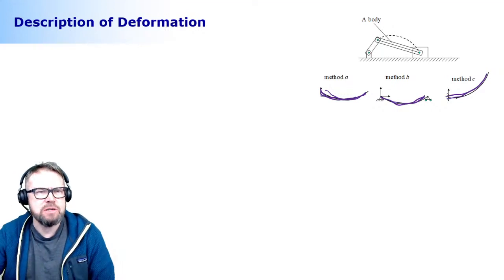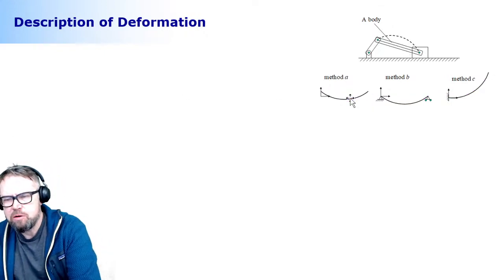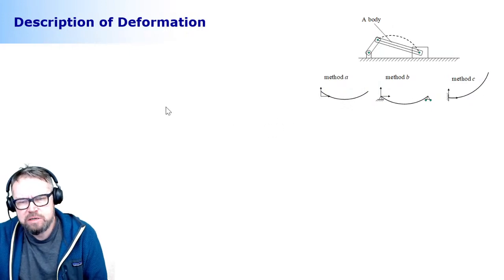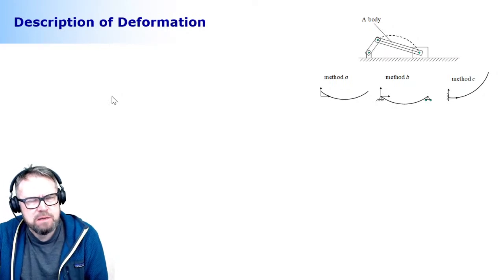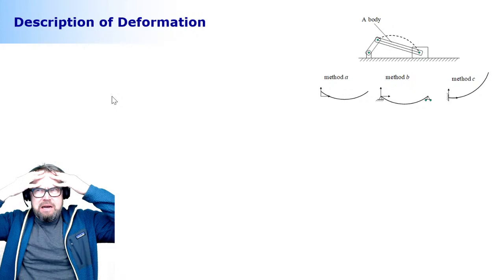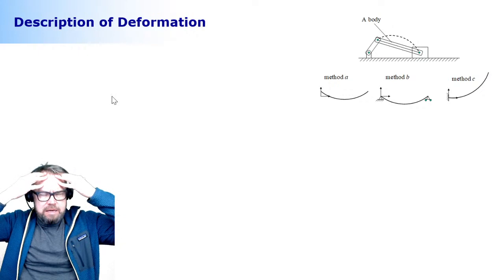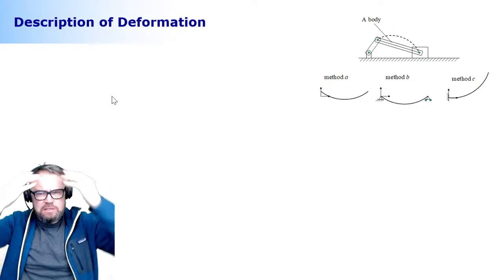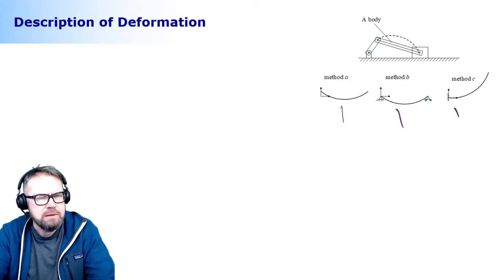Now, how they are attached to the body reference coordinate system is what is called the reference condition. And it's very surprising that each of them eventually produces roughly the same result. This is very, very confusing. Like, what? How come? Isn't it so that each of them has a different natural frequency? Yes, each of them has a different natural frequency. So if you look at the natural frequency, it shows that this and this are not the same. But the deformation modes look pretty much the same.